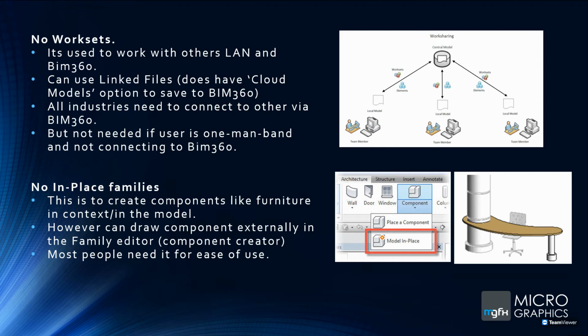That sort of functionality isn't in Revit LT, meaning that you need to create this desk as a family externally in the family editor, and then load it in and place it around the column. So the workflow is a little bit longer, and a little bit harder because you don't have the context to design your components around.